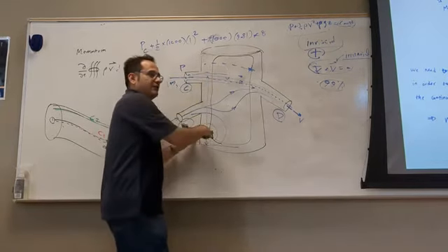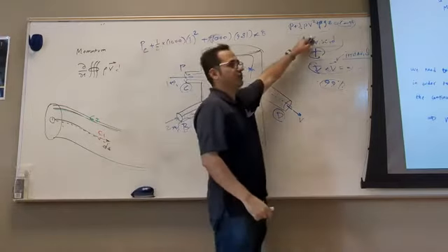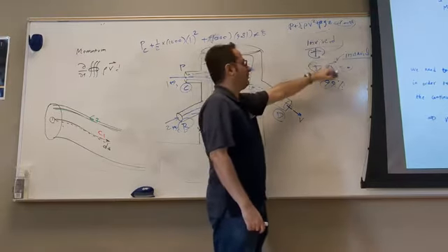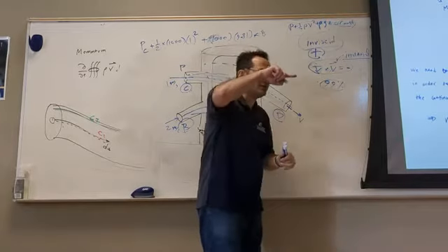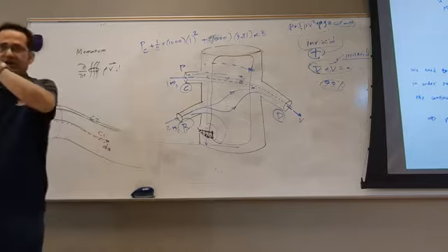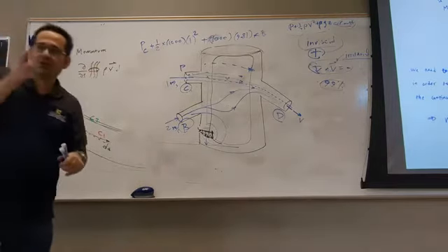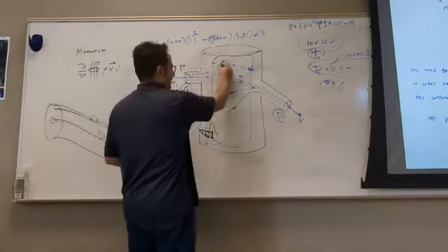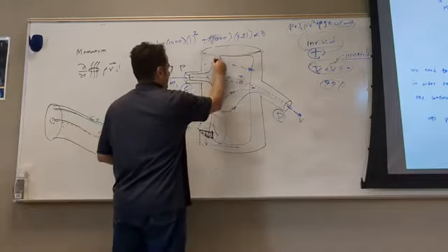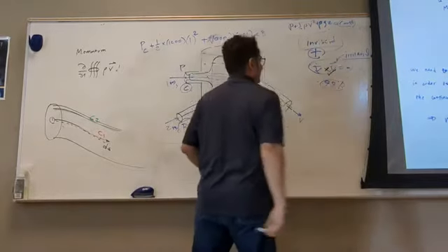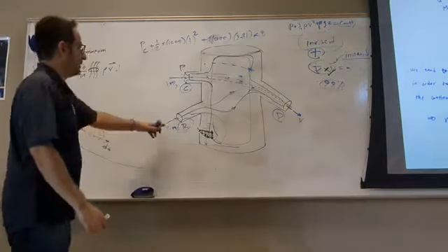Near the wall, you have viscosity. First of all, the Bernoulli is not valid. But even if it was valid, you also have rotation. The flow particle will rotate. You have seen it when they have a plate, they move it, and the particle gets rotated. But here it's very safe. And also here, like an envelope like that. So make more assumptions, irrotational, and then you can write Bernoulli between different points.